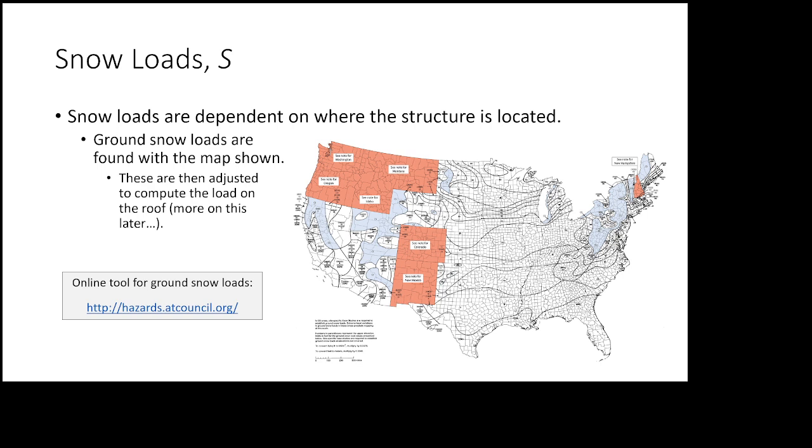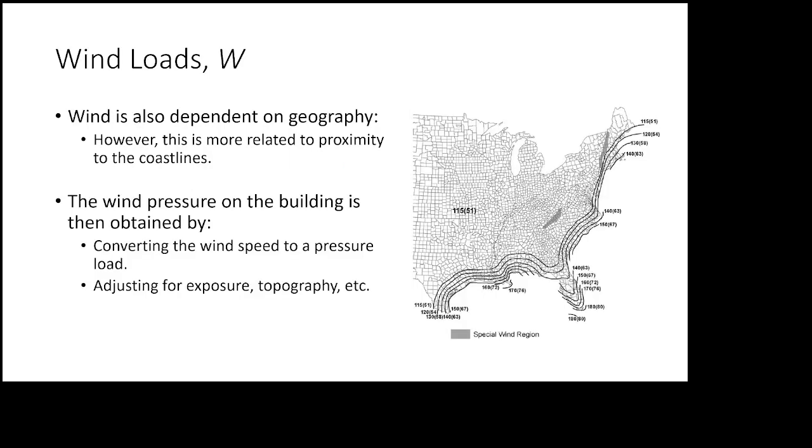This is a really cool tool that integrates with Google Maps, and so you can put in the address. I'm building Geico's new corporate headquarters, and it's going to be in Fairfax, Virginia. So I can put the coordinates, the street address for where the building will be, and it'll figure out, it's right there. The snow load is 25 pounds per square foot, something like that. Now, what happens with snow loads, I hit the button.